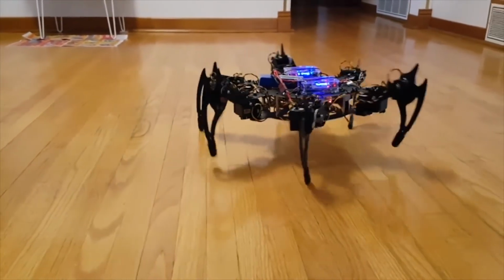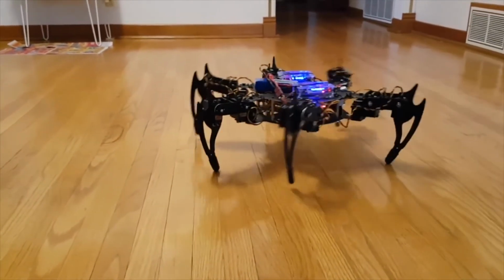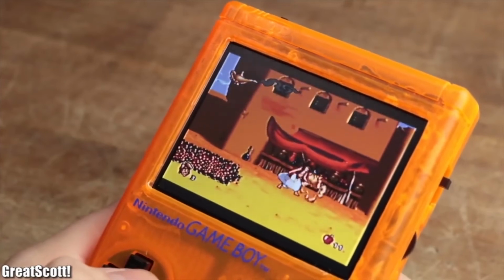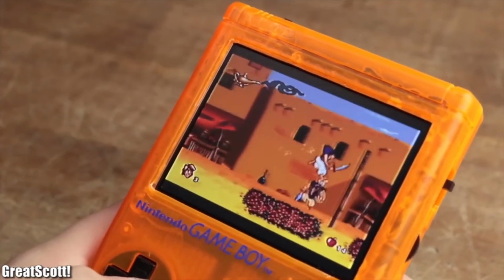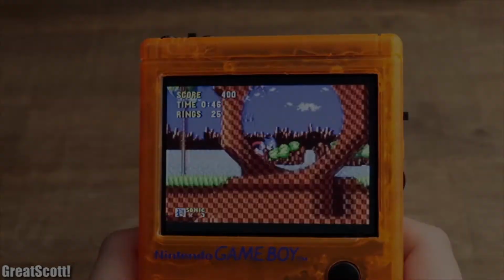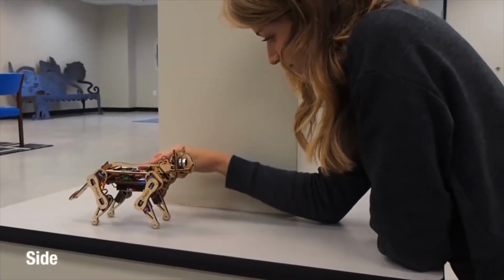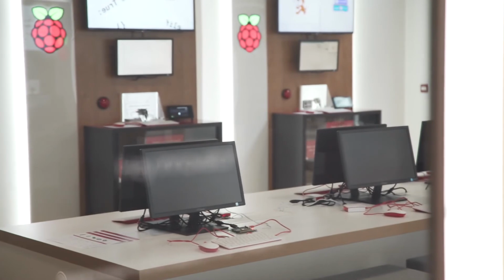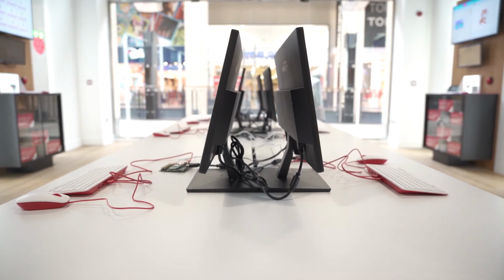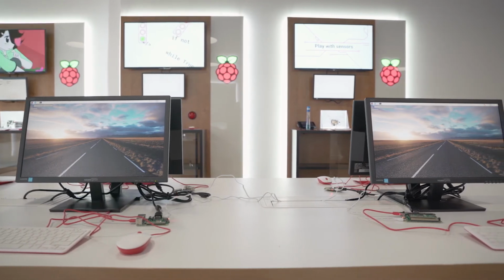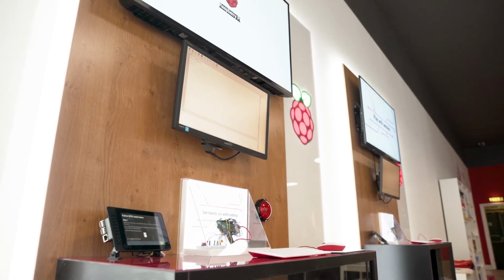When comparing a Raspberry Pi with something like an Arduino, the performance is better. But still, when looking at the bigger picture, Raspberry Pi lacks the power to do intense and heavy tasks. Raspberry Pi only has 1 GB of RAM, which is quite low when compared to other single board computers offered by the competitors. Also, when considering the IoT field where Raspberry Pis are very commonly used, the power consumption is quite high. Raspberry Pi may use 5V, but it requires 2 amperes, which is quite high when you want to run a system on the battery.